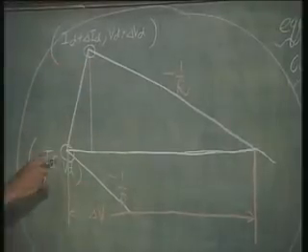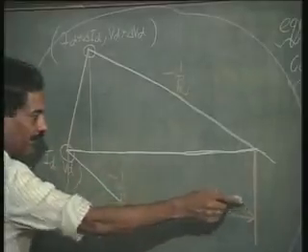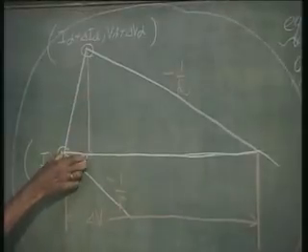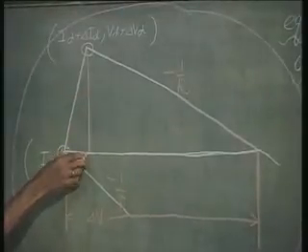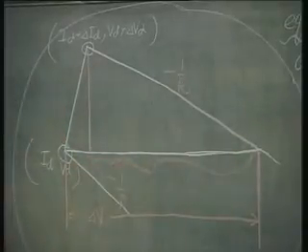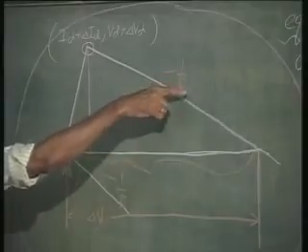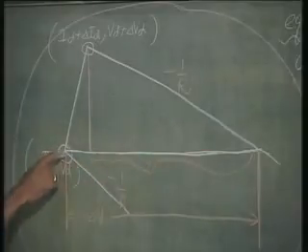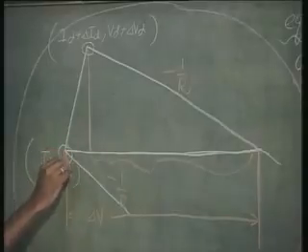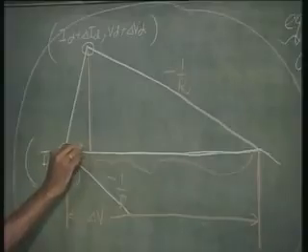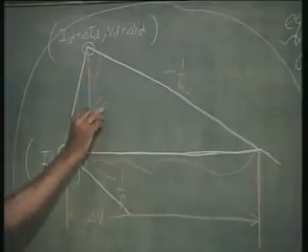The total change that has occurred is delta V. If I now draw a line like this, this change is due to the diode, and this change is due to the resistance R, because that is very clear. This is minus 1 over R. So, the change in voltage across the resistance is this, and the change in voltage across the diode is only this. So, this is delta V diode, this is delta I diode.